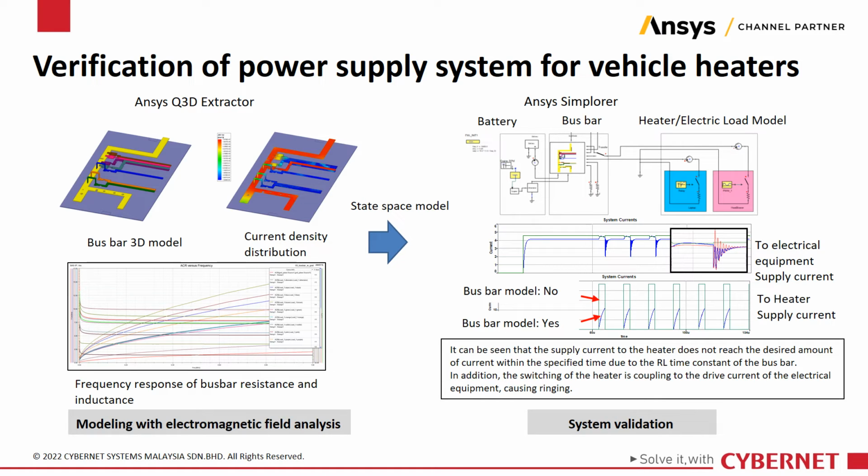Next, it can be observed that the drive current on the electrical load side has a ringing noise due to coupling of the switching pulses of the heater. Thus, by verifying the system considering the parasitic components of the bus bars, it's possible to verify at the design stage those aspects that cannot be evaluated by circuit simulation alone.